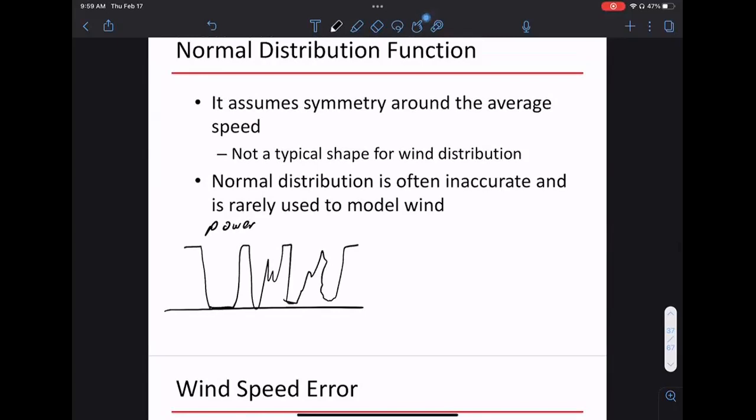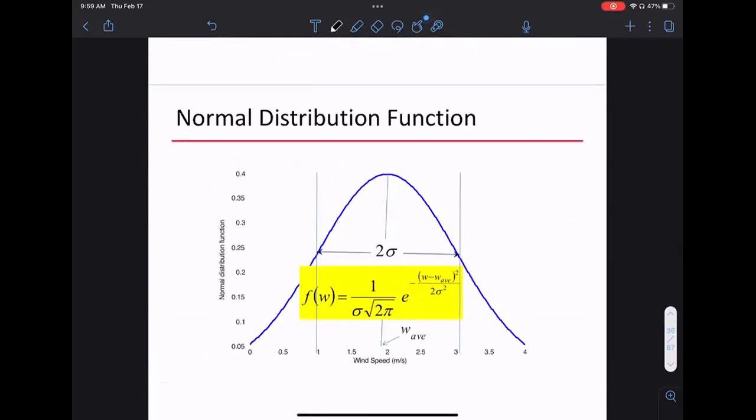Here's what happens: you hit steady-state operation. Remember, for a range of wind speeds you're all putting out the same power. That's why you see this saturation, and it tends to saturate very often. For a range of low speeds it doesn't do anything, because you don't hit the cut-in speed, so it tends to be zero for a bunch of the time. It doesn't spend very long in the middle. It's either saturated or zero. So in no way does it look like a Gaussian.